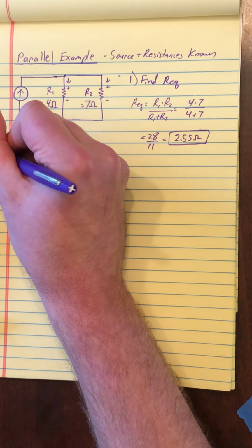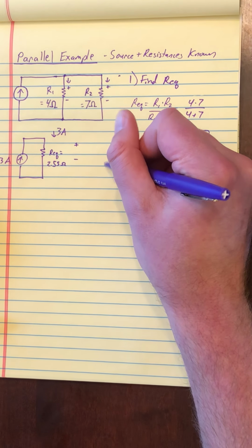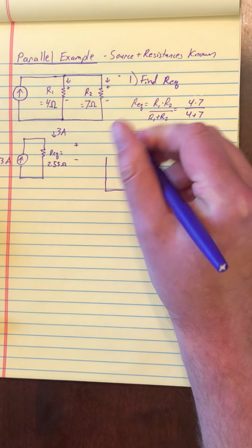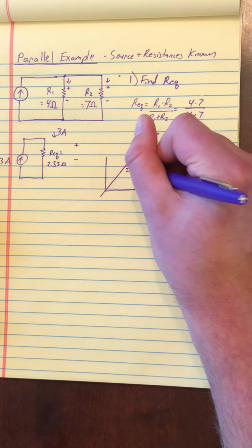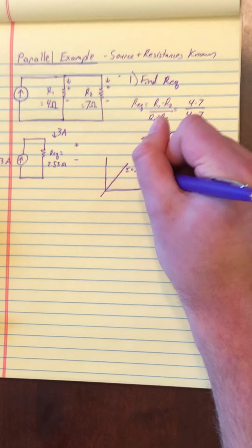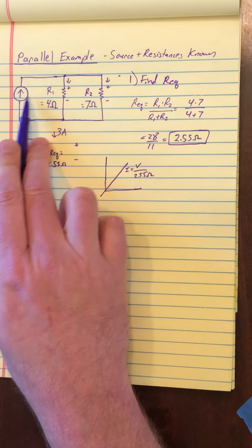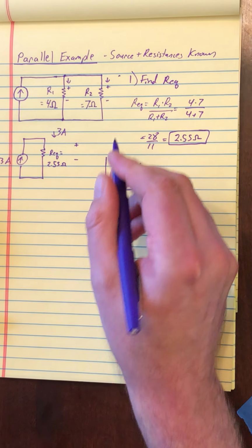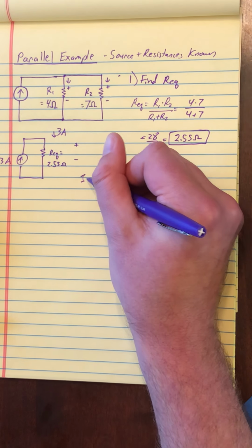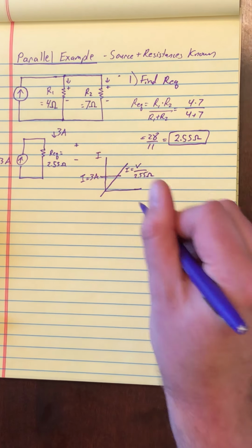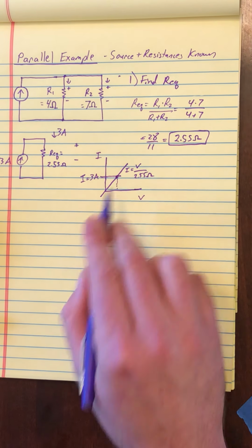So to find that voltage here, we're in essence going to be finding the operating point. And so just like we did before, I have my IV characteristic. There is the equivalent resistance. So this I is going to be V over my equivalent resistance, which is now 2.55 ohms. And this time, we have a source that's a current source. And so I know the I value, so coming around this way here, this I is going to be 3 amps. Again, this is current and voltage here. So I found my operating point by finding the intersection there.